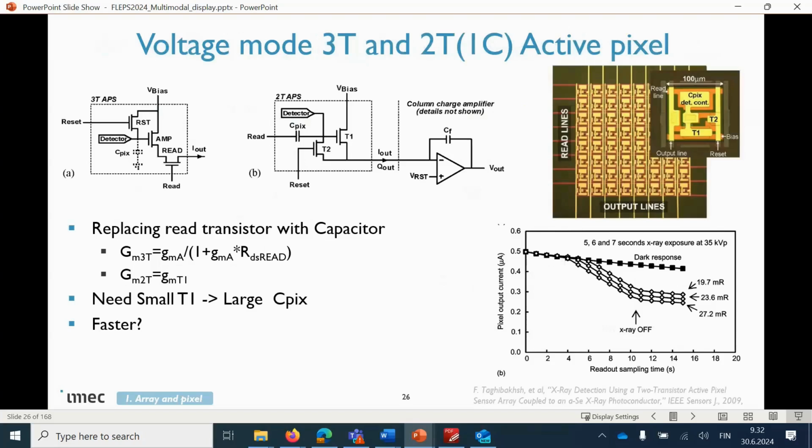And people have been publishing on this. People have already for almost 20 years been talking about improving the passive pixel. The team in Canada, Professor Karim, for example, even went a step further and replaced one of the transistors, the select transistor, with a capacitor. And they even fabricated and tested this. What they did is to use a pulse on the read line here, which runs through the whole array, to pulse the capacitor and read out the charges that you have on each pixel.